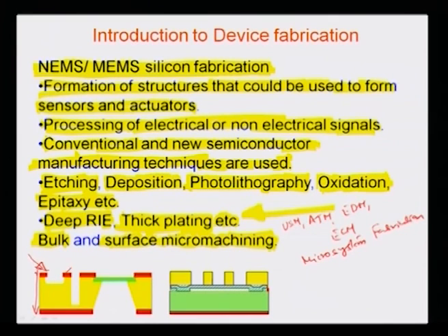So, there can be, for example, a protective layer here which you have etched out and created a small crevice or a cavity. Another example is this particular etch pit here, which is a high aspect ratio structure, and this can be obtained by a process called deep reactive ion etching, where the power of plasma can be used for driving atoms in a particular direction, so that they can knock off the surface atoms here, and based on that high aspect ratio structures can be formulated.